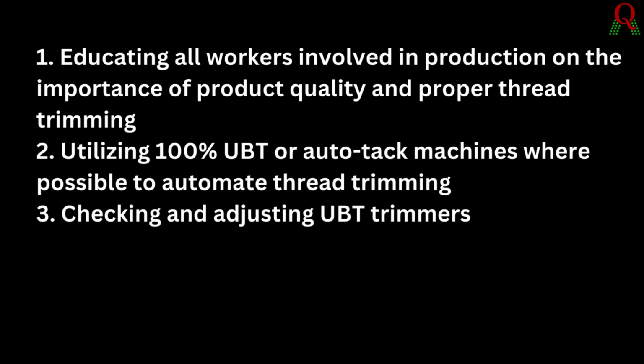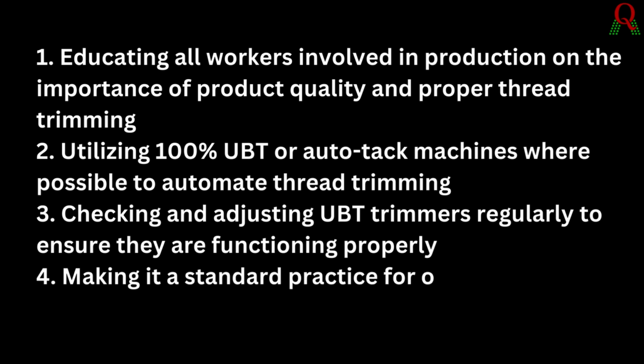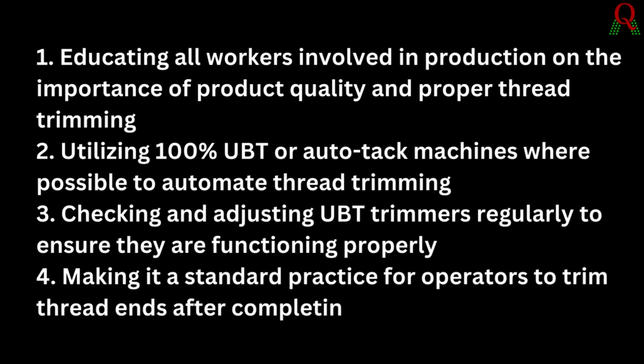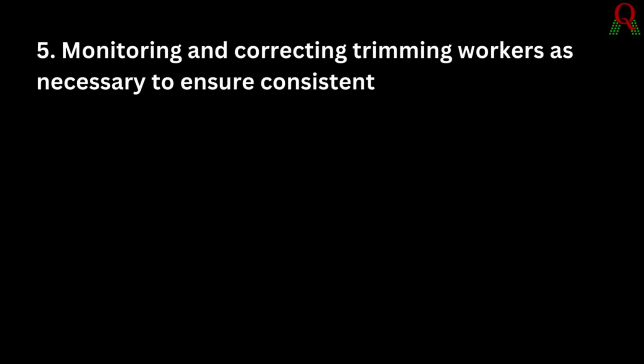Checking and adjusting UBT trimmers regularly to ensure they are functioning properly. Making it a standard practice for operators to trim thread ends after completing sewing operations. Monitoring and correcting trimming workers as necessary to ensure consistent and thorough trimming.